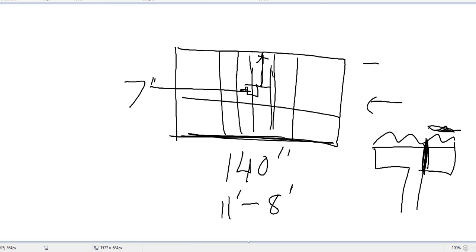Now you can consider a 1 foot strip, no problem, and whatever reinforcement you'll get here, you'll copy paste all over. You can do that, but it's a good idea to do it for the entire width. And there is a reason, because for rectangular footing in the short direction we have some other story, we will tell that.